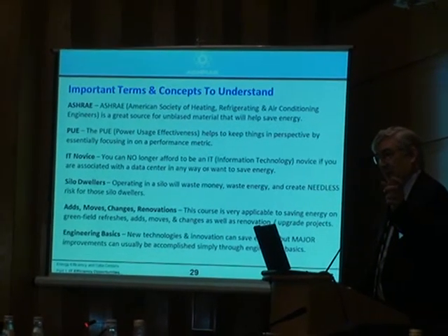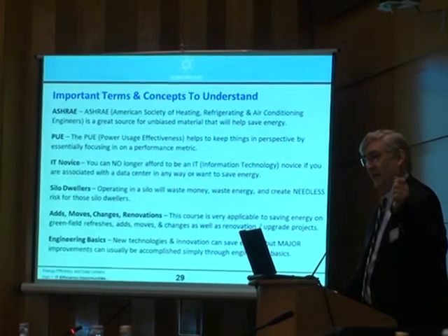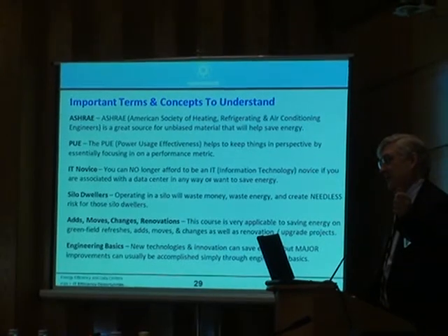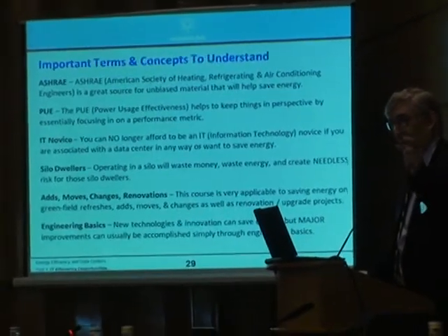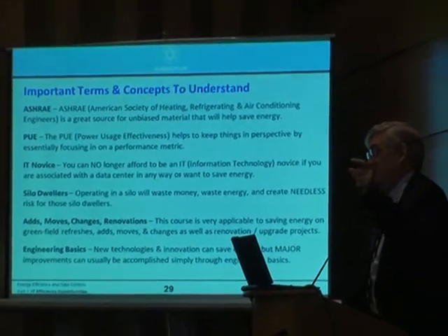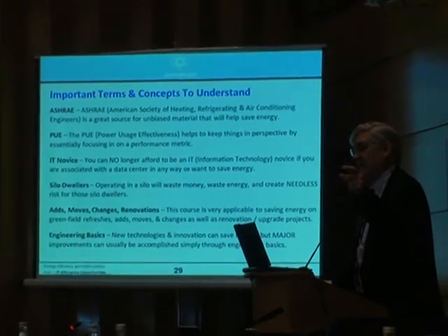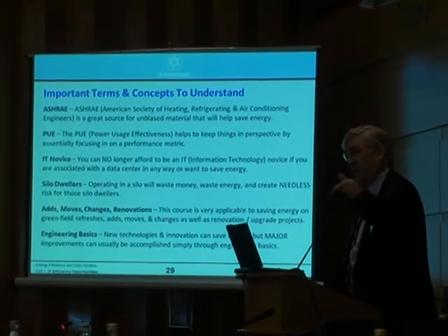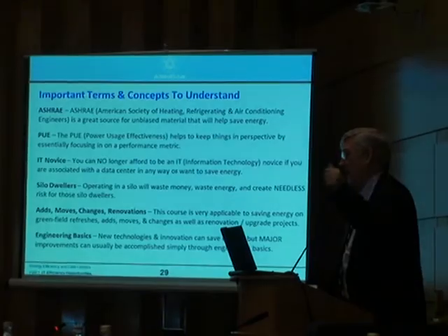For the enterprise data centers, like what the vice president of the bank talked about this morning, where he had a lot of redundancy and could not have a data center fail. He had to have disaster recovery and a lot of redundancy. That data center may be designed somewhere between 1.4 and 1.6. So it has more redundancy, more equipment. You can't probably have the lowest PUE in that sort of data center. So internet data centers may be a very low number, like Don talked about, 1.1, 1.2. Enterprise data centers are going to have a higher number.